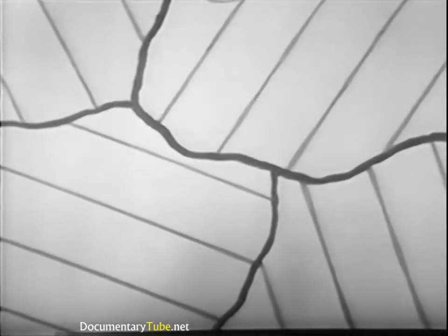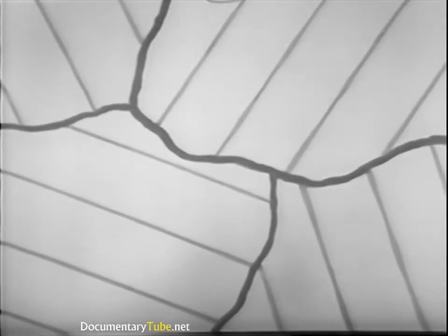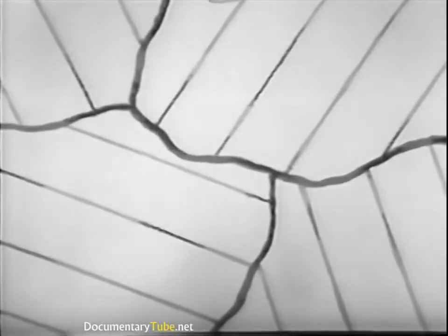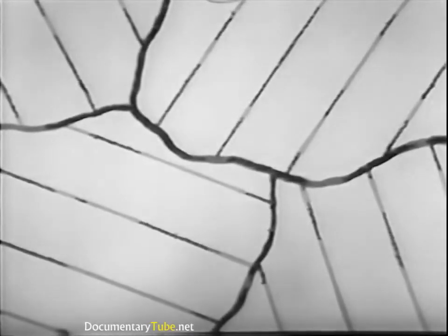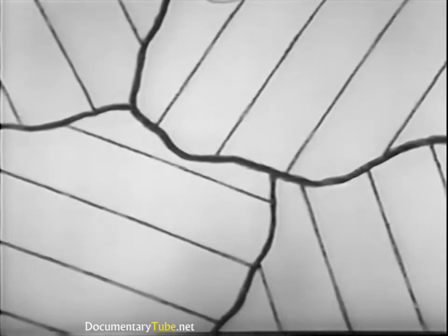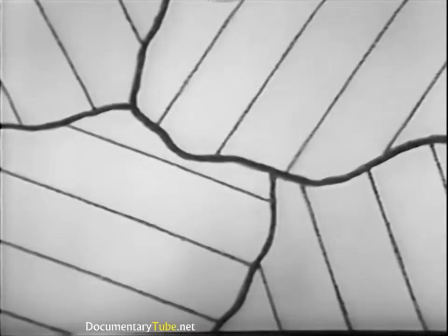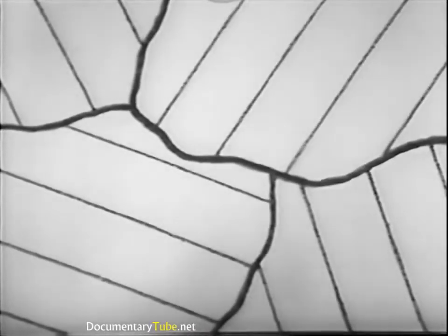One explanation of this effect is that disturbance along the slip planes and grain boundaries produces an amorphous material having no crystalline structure and therefore no planes of weakness. Thin layers of this material, stronger than the parent alloy, form along the slip planes and grain boundaries and serve as a cement to bolster resistance to further slip.